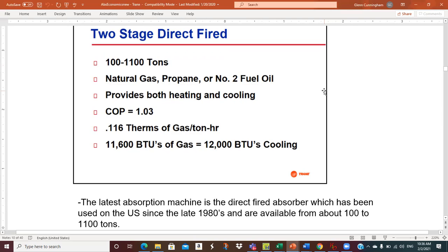As the number on the fuel oil goes up, the viscosity goes up. A fairly common boiler fuel is number 6. Number 6 fuel oil will not flow if you don't heat it. It will turn into something like molasses in the pipes if you get it cold.